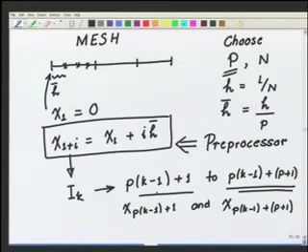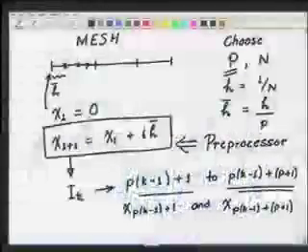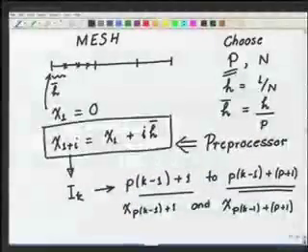That's why generally in the 1D approximation where we use this kind of Lagrangian shape functions, these nodes, which were the solution points, are indistinguishable from the geometric points. So they are both called nodes. But the solution value is called the degree of freedom. So at every node there is a corresponding degree of freedom, which is the value. So the problem has np plus 1 degrees of freedom or unknowns.